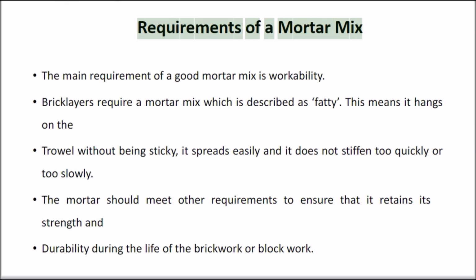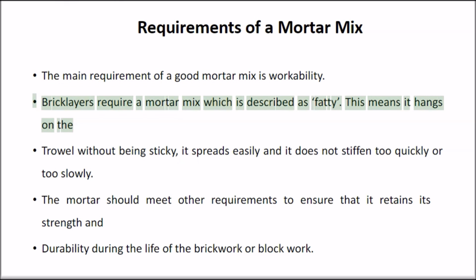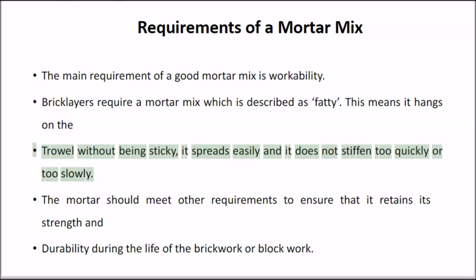Requirements of a mortar mix. The main requirement of a good mortar mix is workability. Bricklayers require a mortar mix which is described as fatty. This means it hangs on the trowel without being sticky.